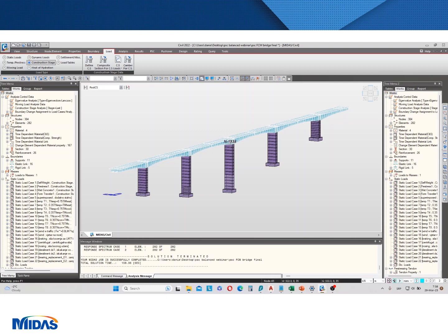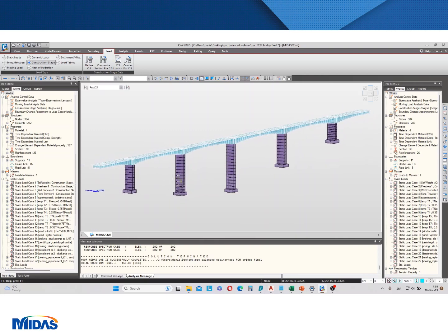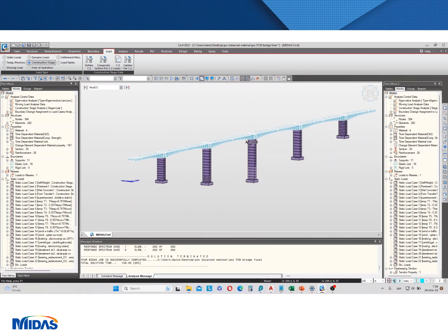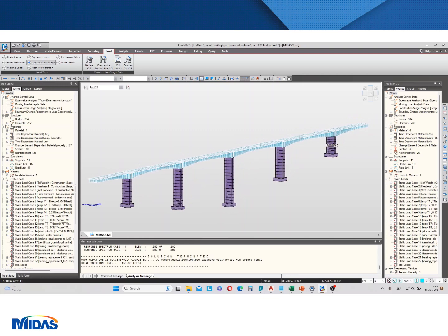Generally, I don't expect any changes in bridge geometry to be necessary. Main focus is on the superstructure, so it is adopted by the recommendations for this type of structure. So it should be fine, except perhaps we will need some tweaking in the tendons profiles or forces. So let's dive into it.